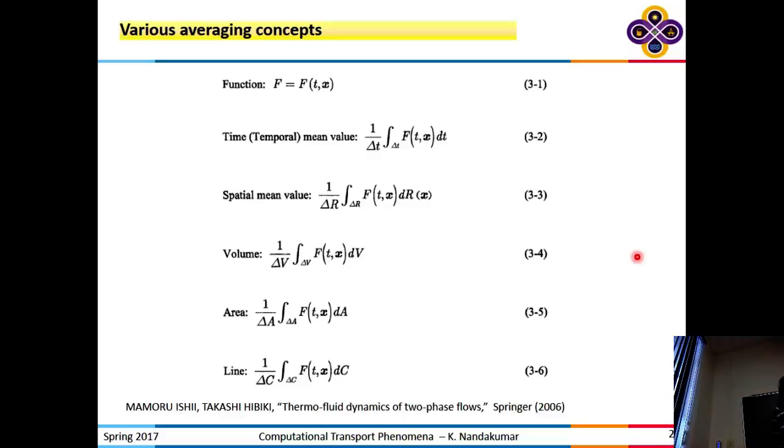And the question is, can I subject these equations, with the time term, rho dV/dt plus this, to the filtering idea? So this is the incompressible Navier-Stokes equation, right? Can I subject these equations to the filtering idea that comes from the geometry of this? So if I take this velocity field, which is a function of time, as a velocity that is average, and a velocity perturbation that is a function of time. So what I'm saying here is, there is a line, and that represents V bar. And from that line, there is a departure. And that is my V prime.